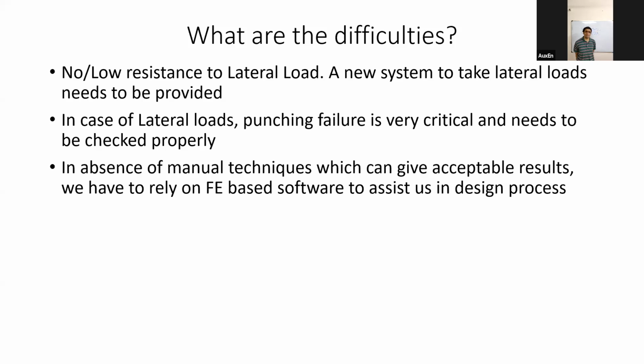generally provided in the form of a shear wall system. So what I'm trying to tell you is that when we are using a flat slab system, it is not enough on its own to take lateral loads. It is only good enough to take your gravity loads. To take care of the lateral loads, we have to introduce another system, which is called the shear wall system. Understood? So you have to have two systems in case of flat slab to take care of lateral and gravity. Your slab column system will take care of your gravity loads. Your shear wall system will take care of your lateral loads.